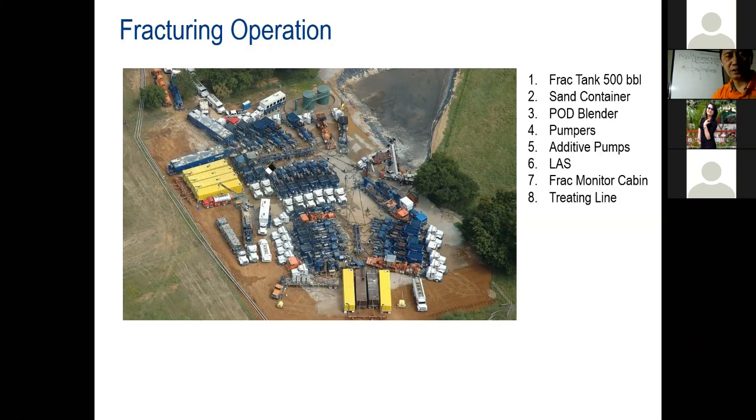Here on the treating line, you can easily see 5,000 psi during pumping, and it's very scary, guys. I mean, very dramatic. When you start pumping, sometimes this treating line is shaking the ground, like boom, boom, boom, boom. You can see all this steel iron with 5,000 pounds in it, or even 10,000 pounds in it, shaking around. Imagine, you cannot miss the safety factor and preparation for this job. Everything has to be pressure tested and everything has to be right. And not to mention the safety concern coming from the chemicals too.